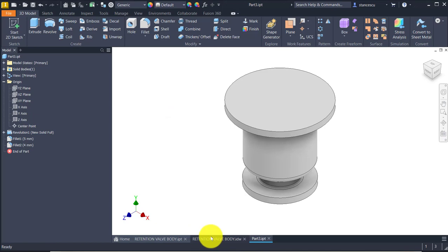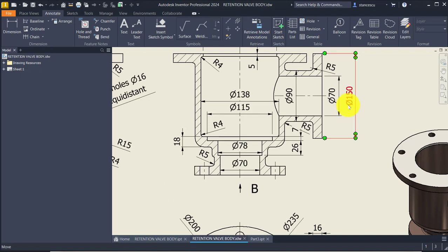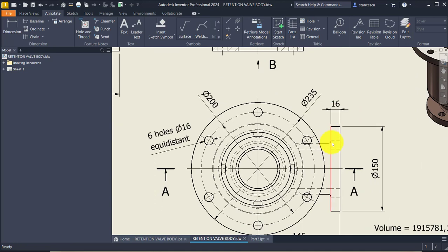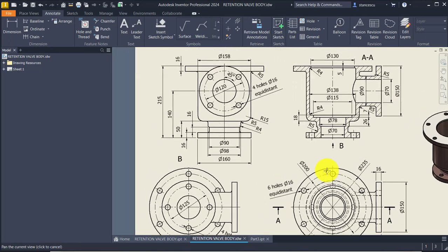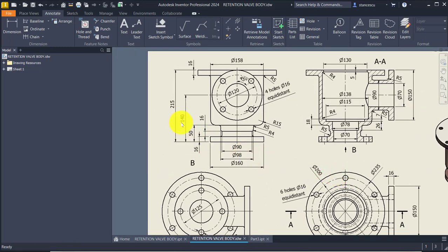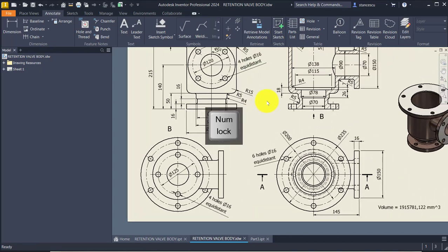Now we create the sketch for the horizontal revolution body. We have dimensions here, diameter of 150, 90, radius 5, this is 16, 150 is twice, no problem, and at a distance of 140, the other distance 145. We use these dimensions.